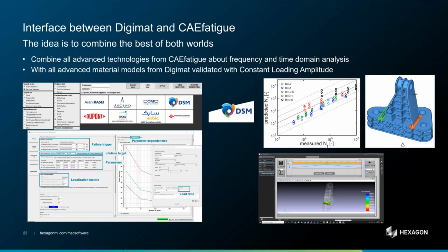This is another example of integration. I did hint at this. When you have a very advanced material requirement, such as in short fiber reinforced plastics, typically you have an initial injection molding analysis where essentially you fill this part with fibers and resin. And what you have ultimately is a different density and a different share of fiber direction depending on where you look in the part. And this information is available, right?